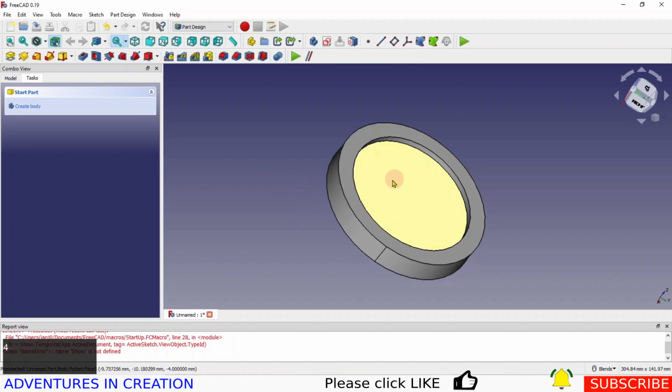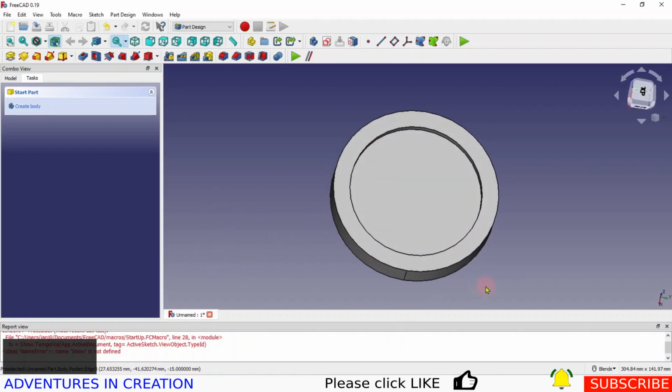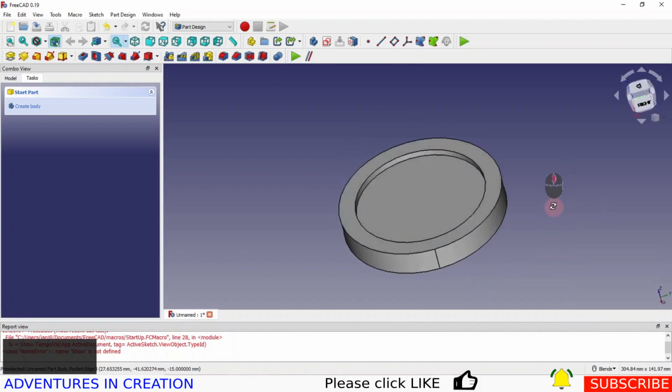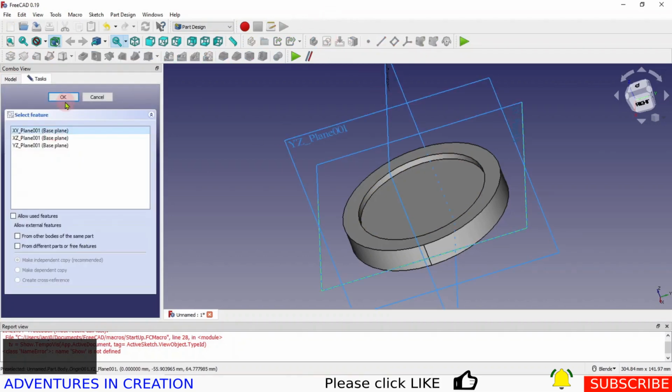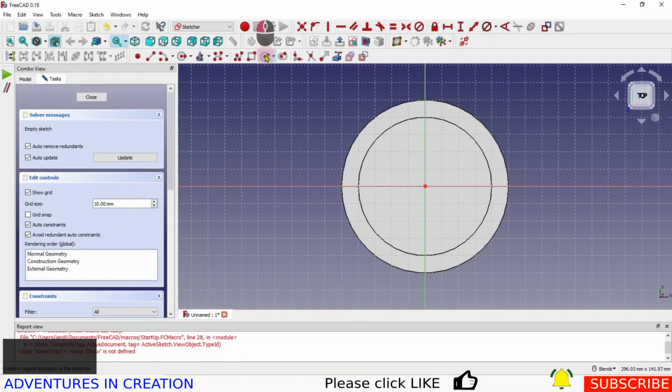What I'm going to do then is engrave something on this front face. Then I'm going to fill it with epoxy to the top surface. So that's the finished article, and I have actually made some, so I'll show you one at the end, what it actually looks like. But for now, we're going to create a sketch that we can use for engraving. So we're just going to engrave around a sketch. And I'm going to do something very simple. Again, on the XY plane, I'm just going to do one of these, a hexagon.